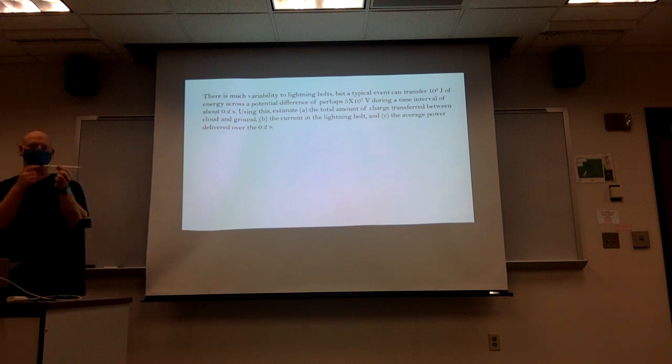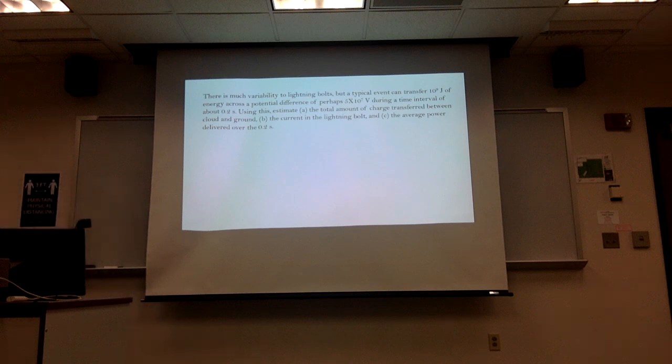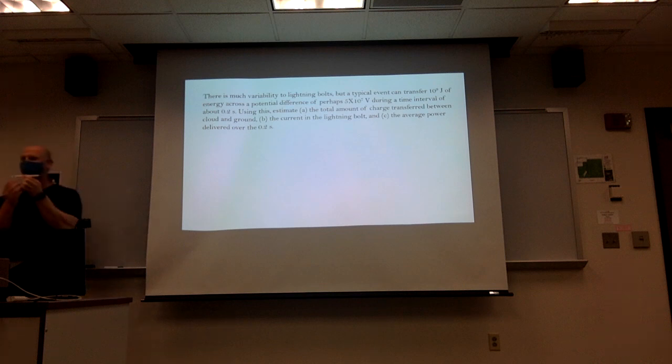The circuit breaker measures the amount of current running through that wire, and if it exceeds 10 amps, it's going to say, this is going to get too hot, and I could burn out the wire or even my entire house. So if it measures using an ammeter that the current has increased higher than 10 amps, it'll kill the circuit, ensuring that you don't burn down your entire house, which would be a good thing. So, let's use that.